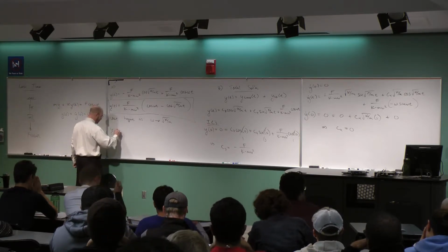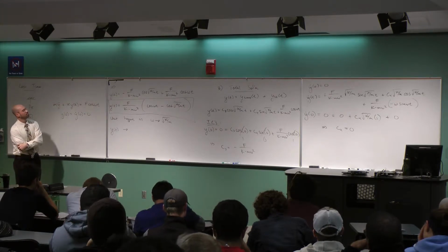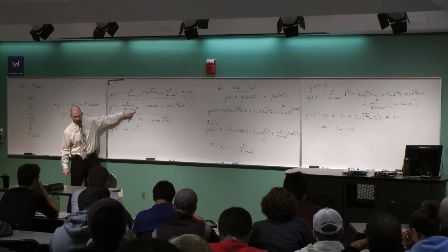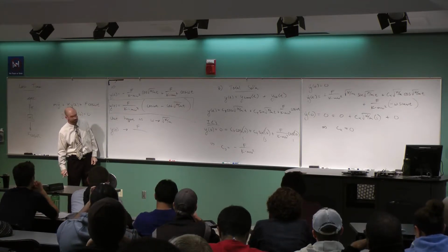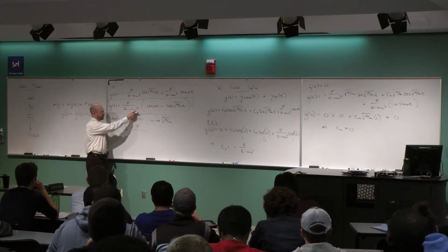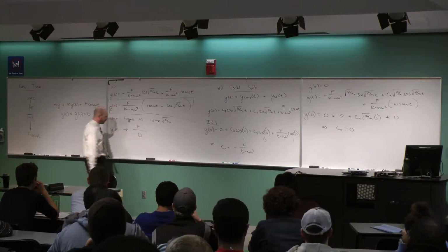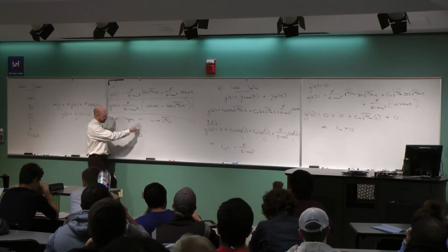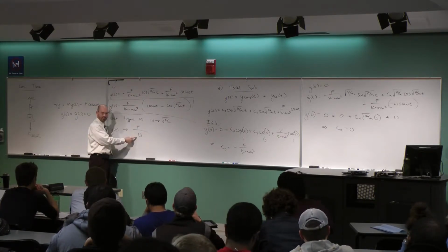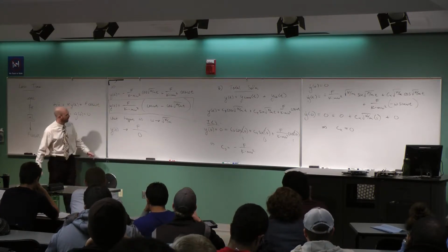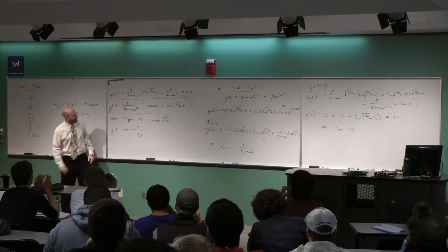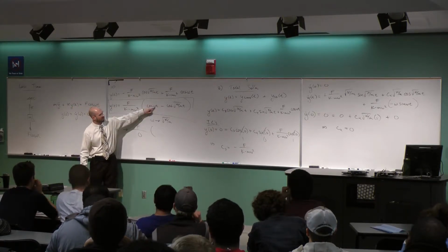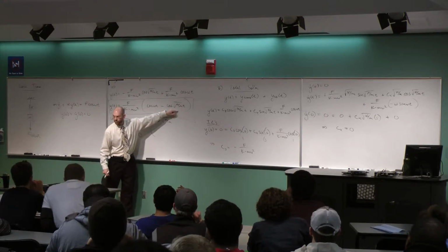So take a look at the math here. What happens to y of t? Well, I still have an f here. What about the denominator? As omega approaches root k over m, this denominator approaches what? 0. I square it, I get k over m, the m cancels, and k minus k gives me 0. So the front looks like that, which is a problem. Note that this is not an equal sign, this is approaches. Denominator approaches 0, so this starts looking like a big number. One thing immediately is that the solution starts to blow up. But it gets a little more complicated, because when this number approaches root k over m, how does this term compare to that term?